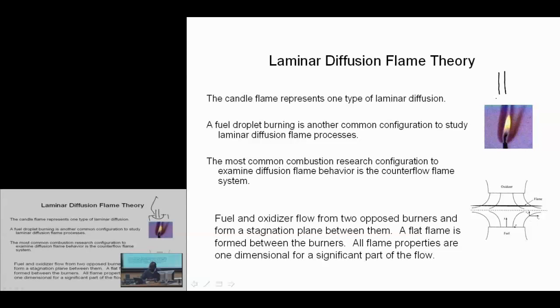So we have a flame supported above a fuel source, and heat transfer from the flame melts the fuel, causing the phase change in this condensed phase fuel. Capillary action wicks it to higher elevations in this wick, and again heat transfer from the flame vaporizes the fuel and allows that fuel to burn with oxygen that is available externally.